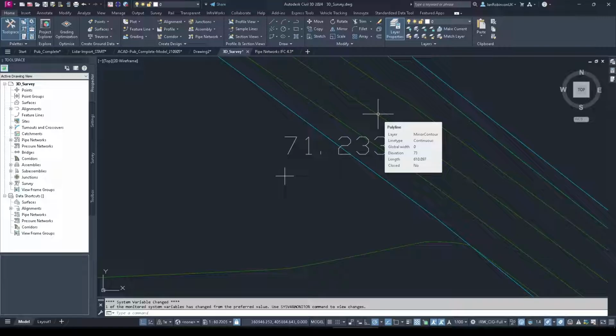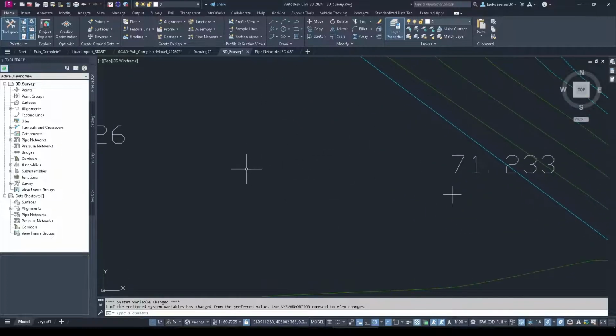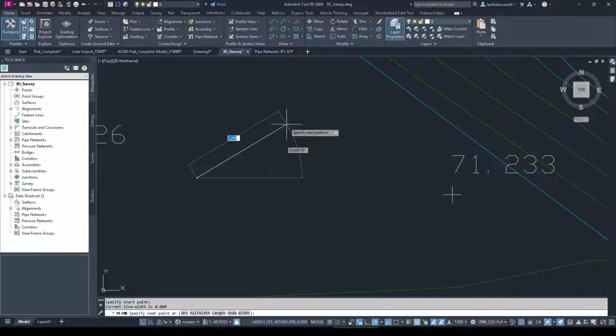Next thing on performance is dynamic input down here, the DYN mode. If you're unfamiliar, when you have that turned on and you start typing, the command line effectively comes up where your mouse is, and you get some very handy measurement tools where you can do distance and you can do angles and stuff like that. So it has its use. It can be very useful.